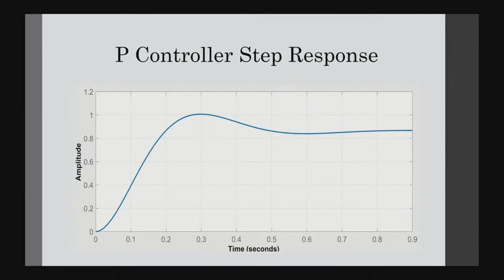For our P controller, it is clearly shown on the step response. There is a steady state error. No matter how you tune the P controller, it cannot be avoided. Therefore, the P controller cannot be used.